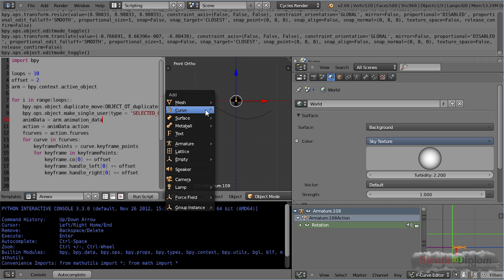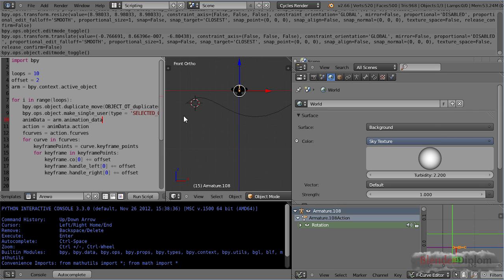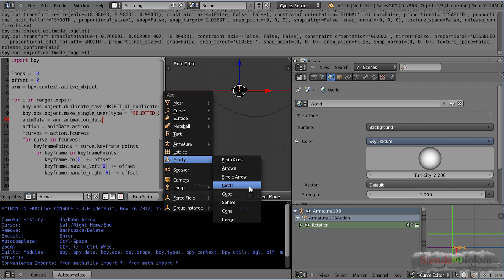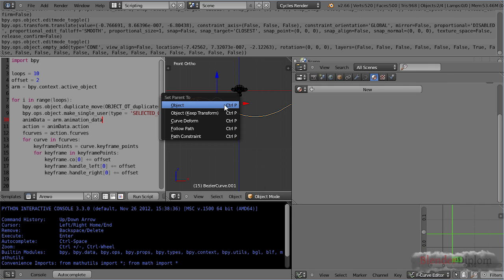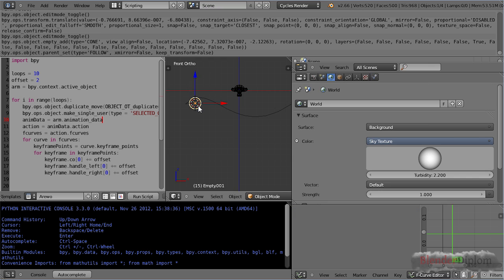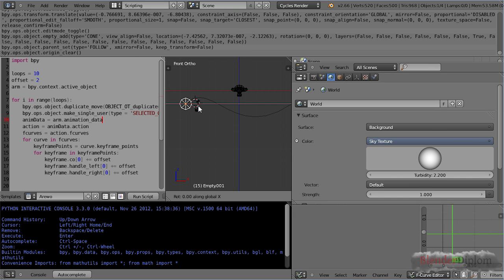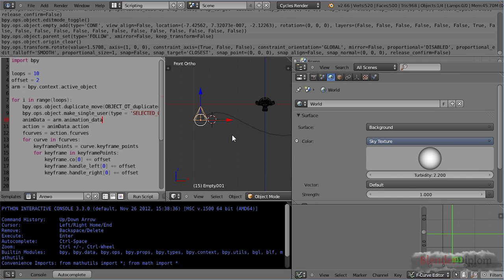The problem with that is the armature will have a different orientation in each frame, meaning if we want all the knights to stand up straight, that wouldn't work. Let me just demonstrate, I'll insert an empty cone here and shift select the path, Control P, follow path. Now I press Alt O and RX90. Now we can see that would be the basic knight, and it is rotating as it follows the path. So those knights would stick like that, and this is not what I want.